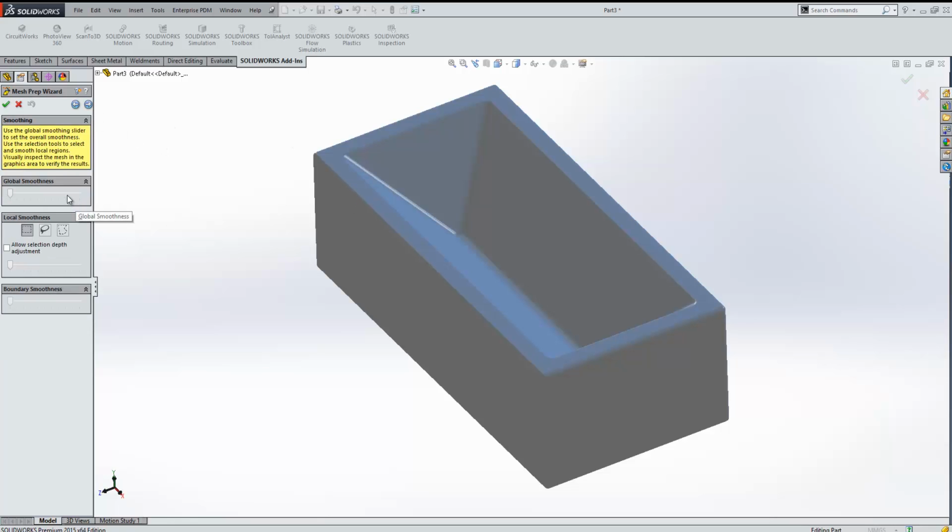We then have global smoothness and local smoothness, and this is trying to make everything flat, which is, on the side of a house brick, brilliant if you wanted to locally smooth it. On our gear transfer case, we've got lots of smooth transitions and changes in height. It's not so good. Global smoothness essentially tries to make everything a flat sheet. So the smoother it is, sometimes good on an area, but over a whole model can cause you some problems.